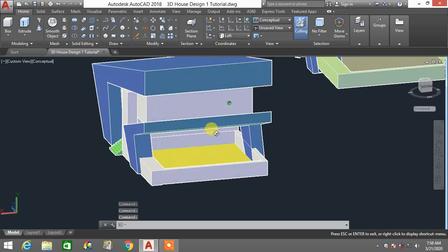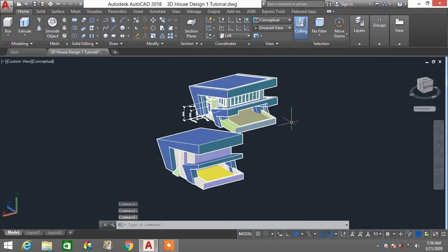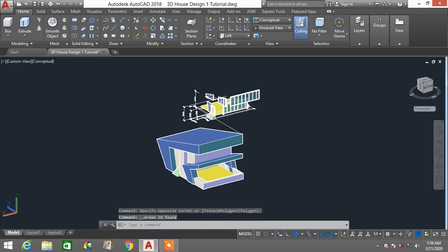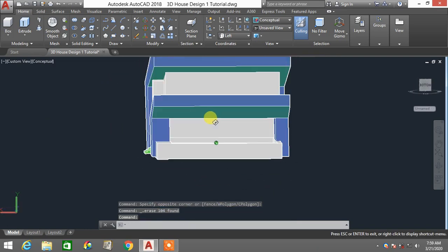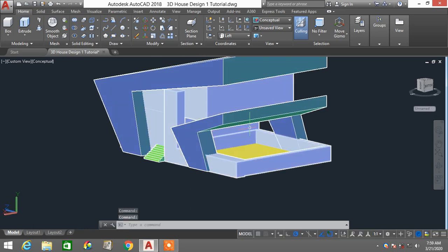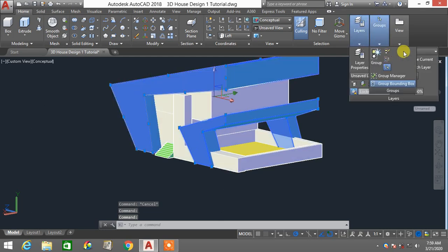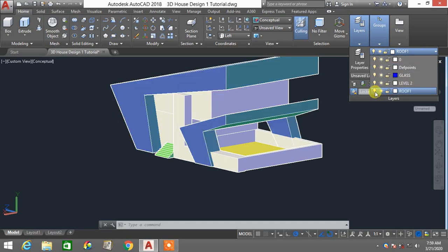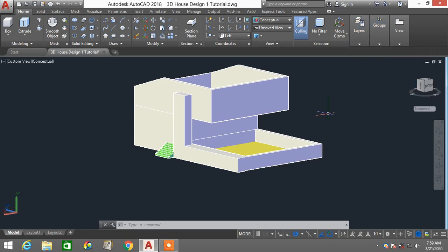Okay, next we are going to draw the window part of this particular house. So I'm gonna delete this original house first. Okay, leaving this design visible for us to see. Okay, let's say you want to make this roof invisible for a while. You can select this roof design and choose a particular layer. Let's say I choose the layer roof. Okay, and I set the layer off. Alright, leaving only the wall structure visible for us to see and to manipulate.